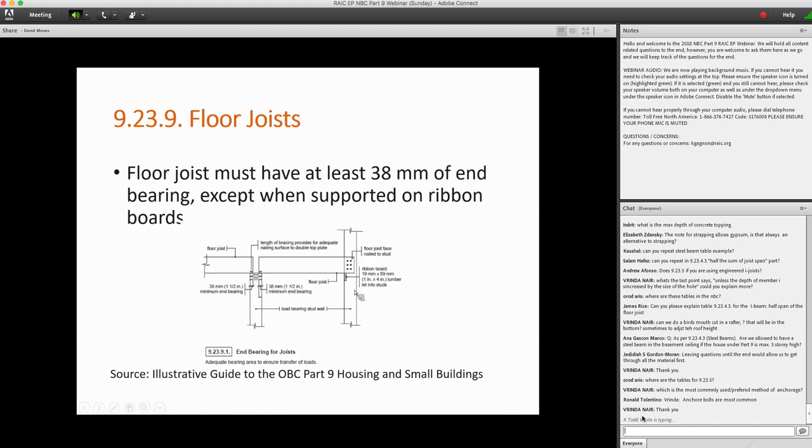And then on the right-hand side, we have the balloon frame. So this is a case where the stud is continuous, multi-stories, and the floor joists sit on what's known as a ribbon board. Some people call it a ledger. They cut the stud, they notch the stud, and they insert this continuous board, and so the floor joist sits on it. But we also nail the joist to the stud, so the bearing is taken by the ribbon board and shared a little bit by the nails, and they provide some additional stability as well.